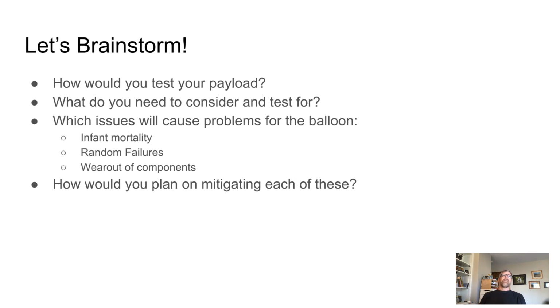All right, so the idea with all of this stuff is that you should sit down with your group, and you should think about how your payload can fail. What are the failure modes of your payload, and what do you need to consider when you're testing your payload? What issues will actually cause infant mortality, random failures, and wear out of components? My guess is that you won't have any components wear out, but these top two are probably really important. And so the idea is that you sit down with your group and think about how you could mitigate against each of those things.